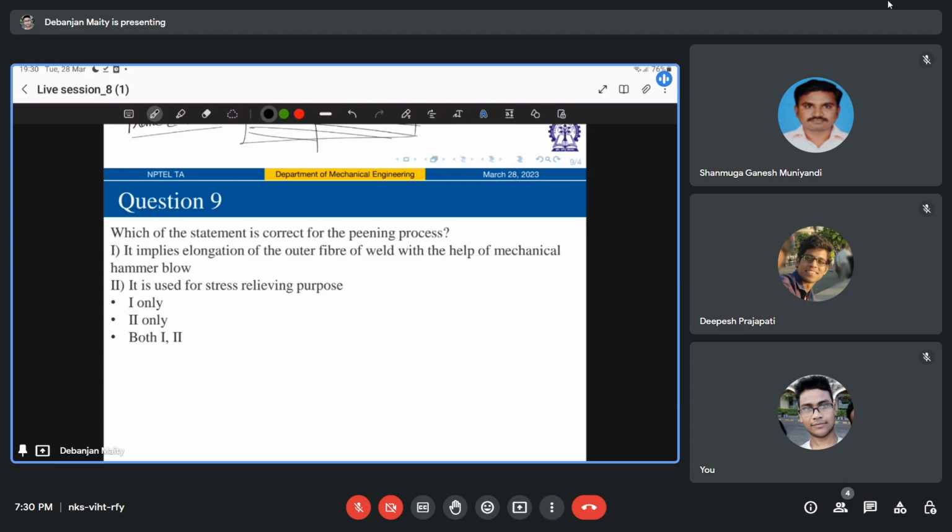Precautions to reduce this residual stress can take two forms. There can be prevention or there can be remediation, right? So to prevent the development of residual stress, it is crucial to reduce the effect of heat during welding. Whatever you are producing in terms of heat during welding, you need to control always to prevent the development of this residual stress, right? So one way, you can employ some cold or non-fusion welding process, but this is seldom a viable option, of course.